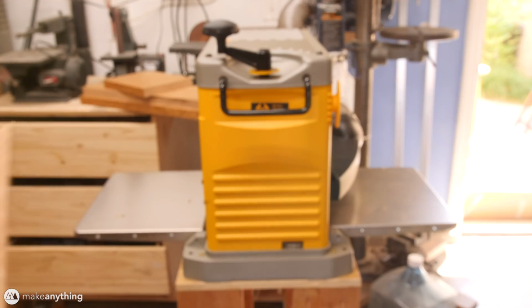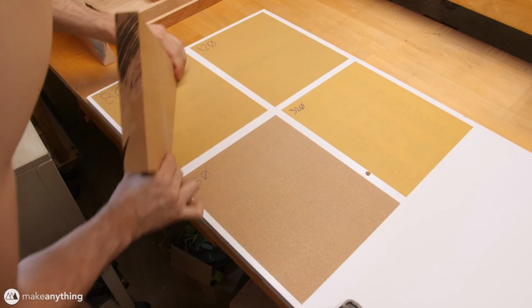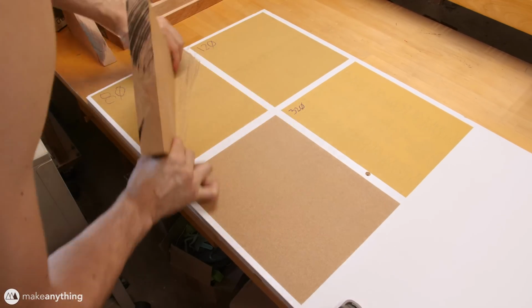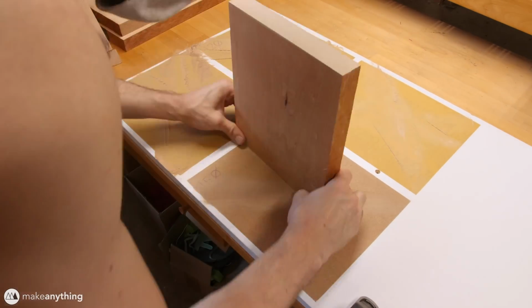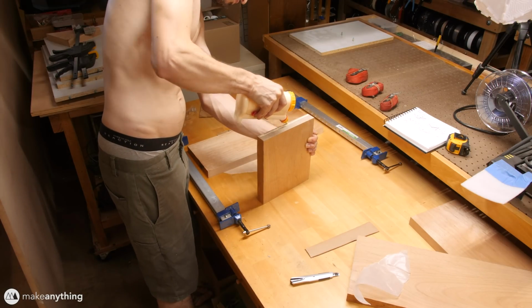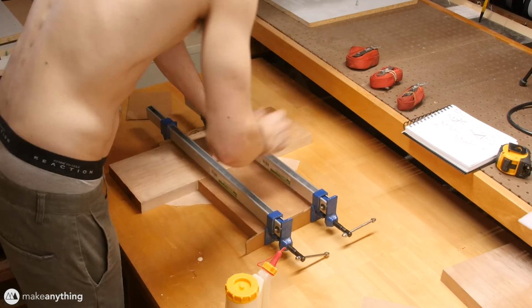Now the sides of the wood are still a bit rough, so before gluing them together, I'm gonna sand this down on this little sanding table I created. It's basically 4 different grits of sandpaper, which I stuck down to this piece of wood using spray mount. And that created a nice flat surface that I could sand against and quickly get these parts really smooth. With that done, it's time to glue these things together. So I'll slop on a bunch of wood glue and clamp the pieces into place.